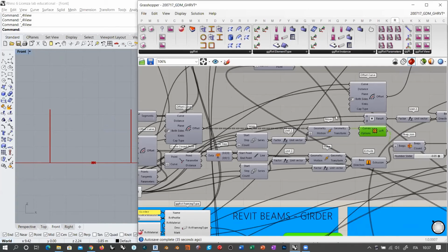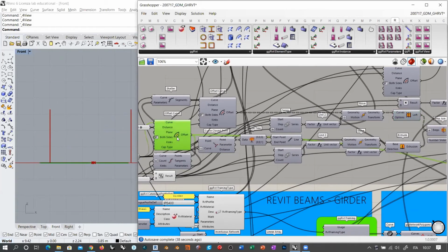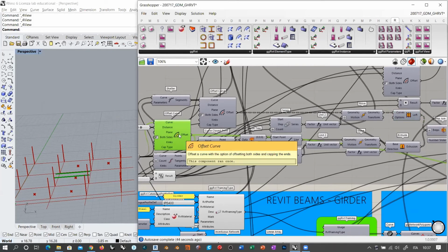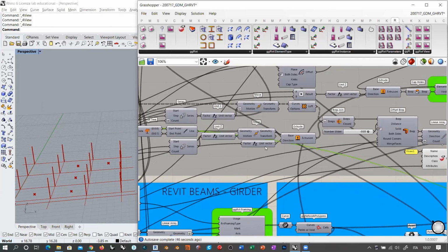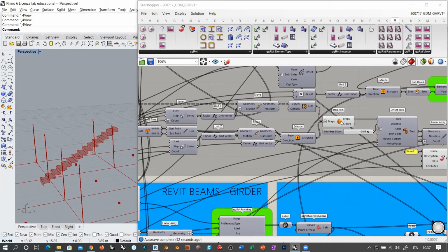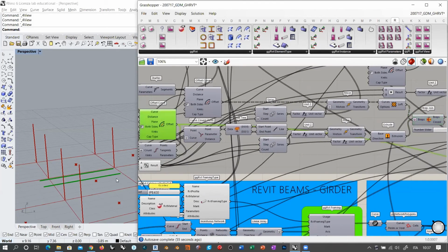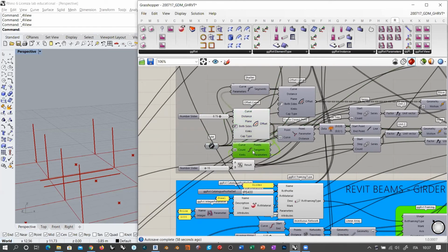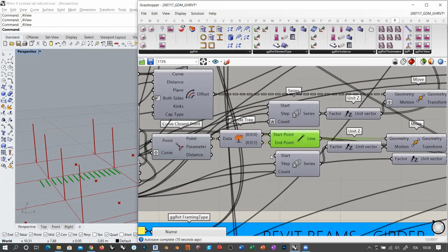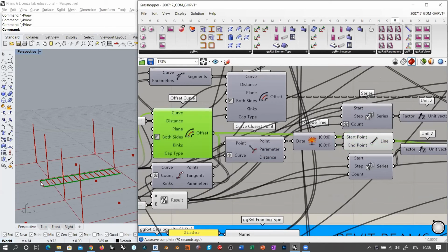And on the other hand, these continuous lines here, there are no internal divisions here. These continuous lines have been used to define the rises. So you see, for example, that I took the continuous line, I divided the axis of this stair into the same amount of divisions as for creating the steps. I projected this point onto the side lines in order to create these lines.